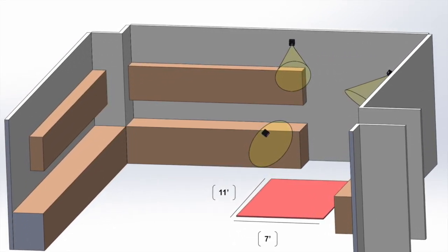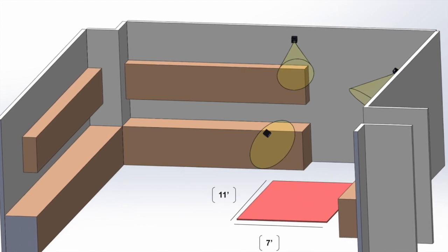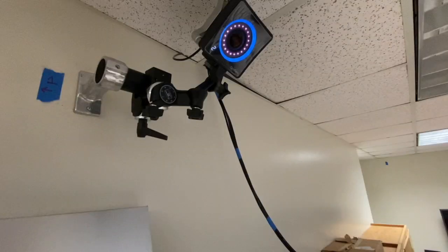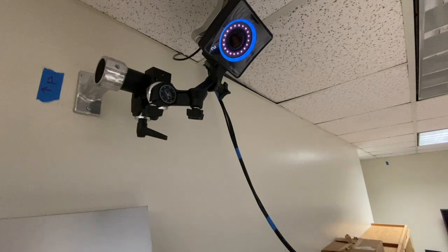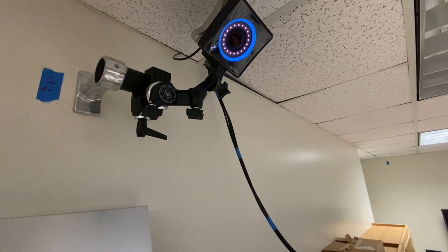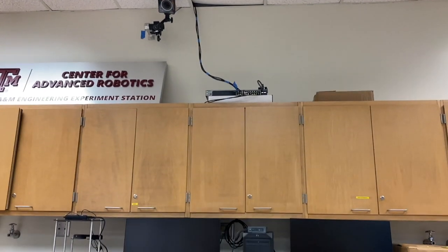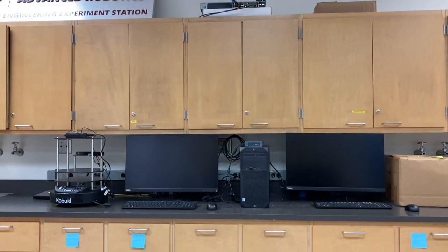Then, using a magnet, we located the building's metal studs and installed 3 degree of freedom mounts as close to our model location as possible while avoiding any studs. The mounts were installed using appropriately weighted drywall anchors and screws after consulting building maintenance, and the cameras were attached to the mounts via set screws. Finally, Ethernet cables were run through the drop ceiling in the room from each camera to a central switchboard that funnels the camera data into the motion tracking software.